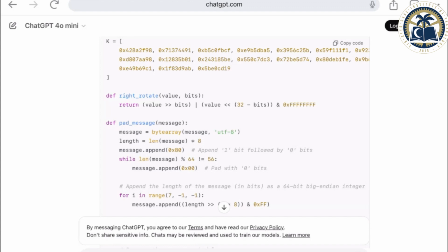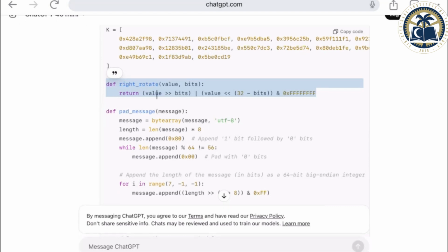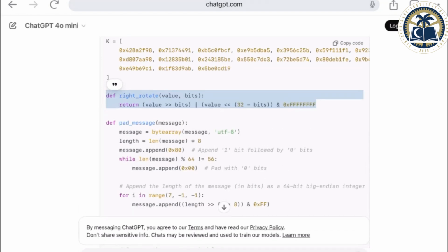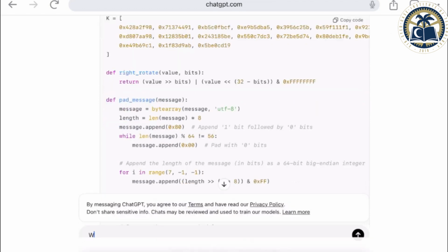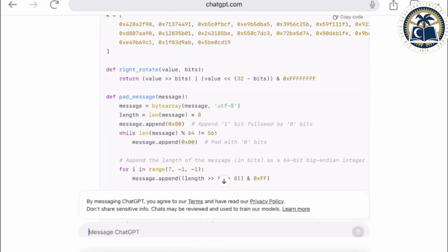What I want to emphasize here is that once we are generating RTL Verilog code, there are two parts to the code. One is the combinational logic, the other one is the sequential logic. Combinational logic is exactly what is here in the Python code mostly. Once you tell it to use Python without a function and generate the code, that is all your combinational logic. Now it has a rotate right function, whose line it has written itself.